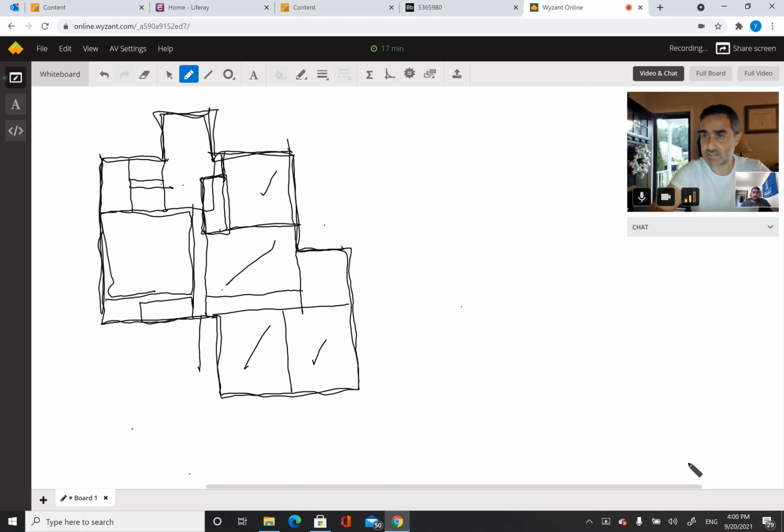If it's a one-way slab, you're probably going to see the beams. If it's a two-way slab, that means it's a self-supporting slab with the beams embedded in it. So you don't see any beams, you just see columns and slab, that's it. But in a two-way slab, the slab is thicker. So there are some rules of thumb that you follow with these types of things.